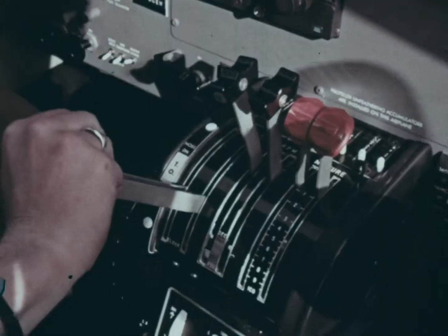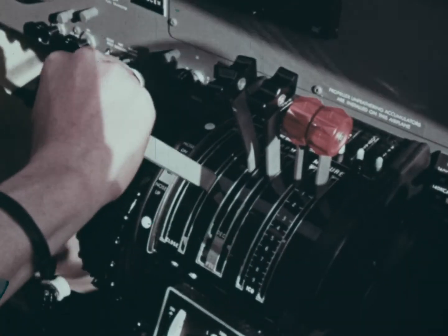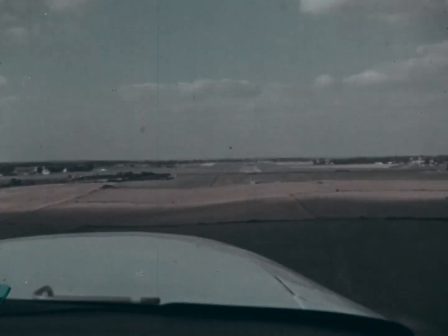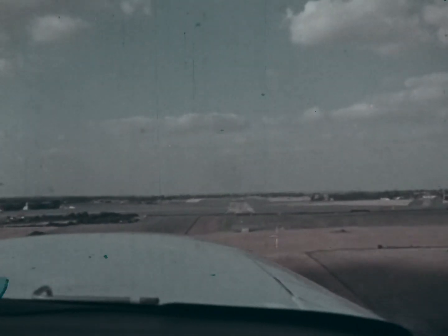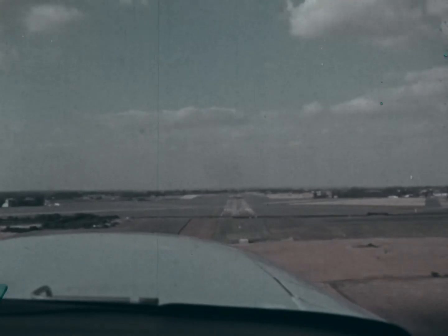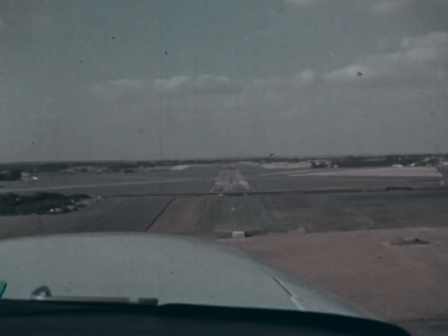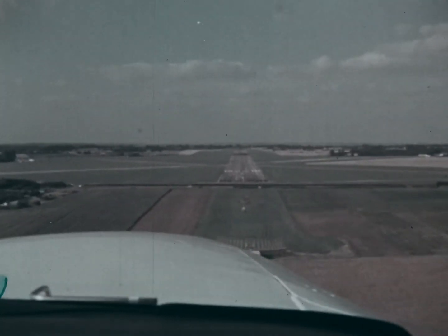This means that the pilot can use the throttles to accelerate air over part of the wing and thus increase lift, controlling the attitude of the airplane in pitch and changing or maintaining height with very little variation in speed.